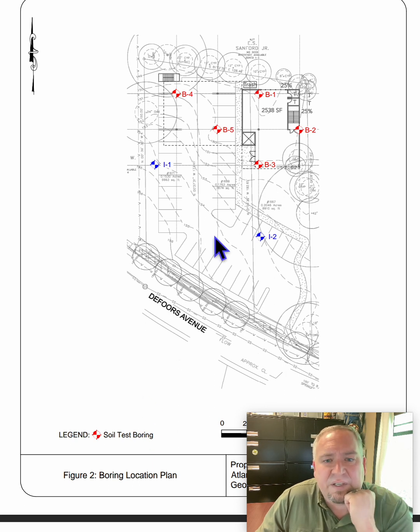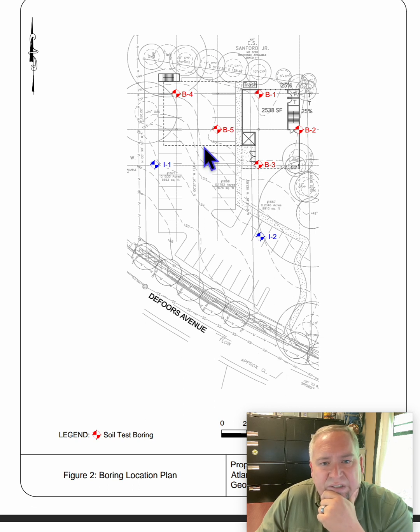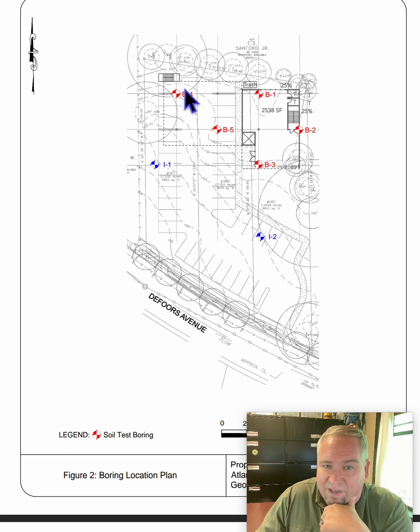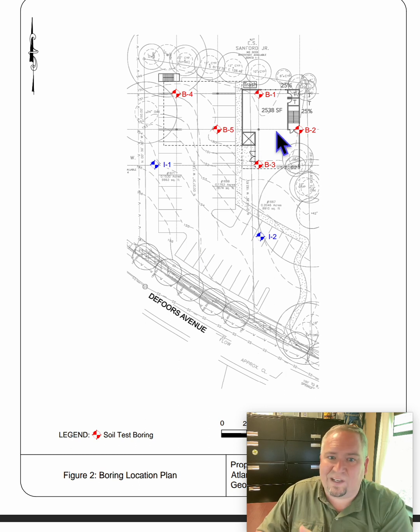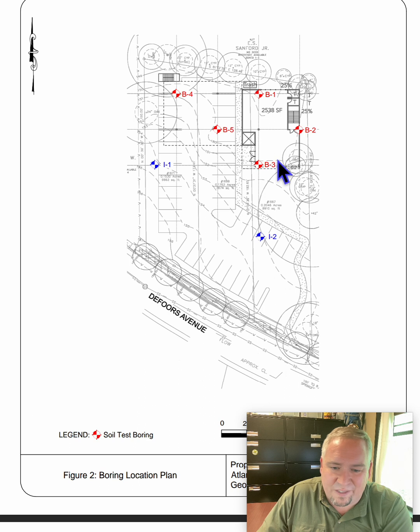So we obviously know that they've got a hard concentration of borings right here, but they don't have anything up here. So the geotech probably noticed no problems or no issues, no red flags up here. But man, they were really concerned about right here. So that trash debris, maybe in the low area or the fill of the dirt, this is towards the back of the property. So this may be a little dumping ground.